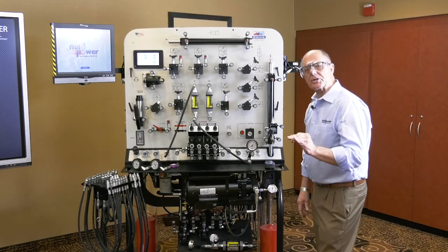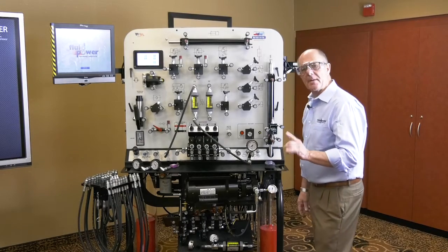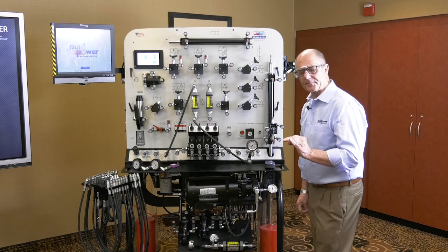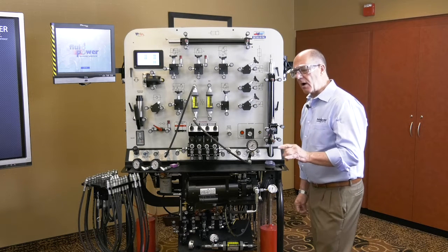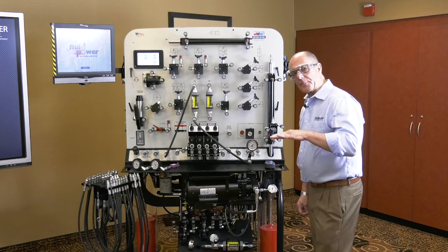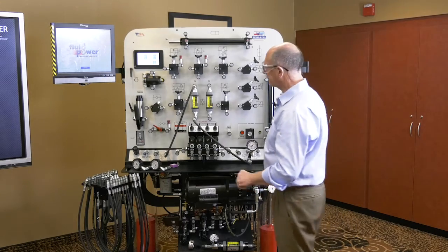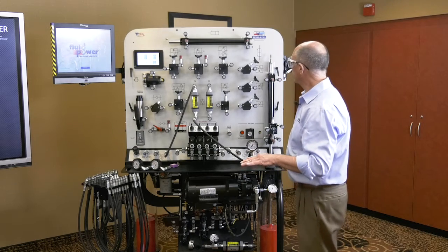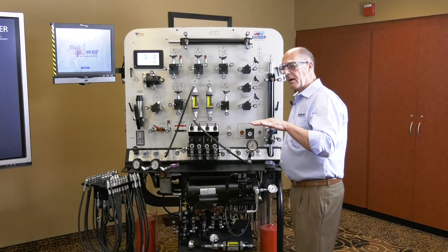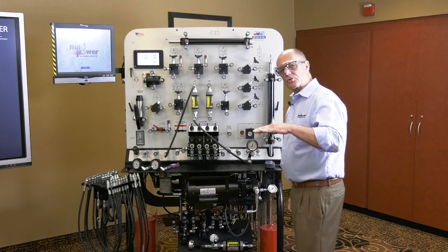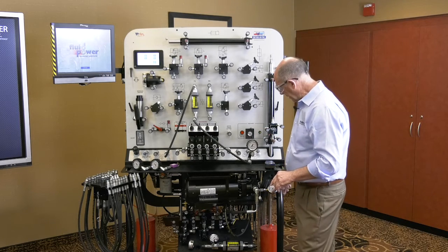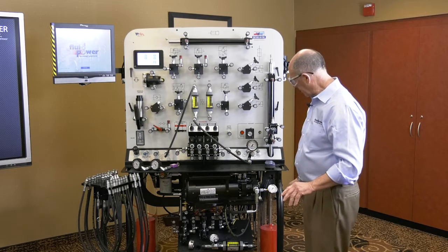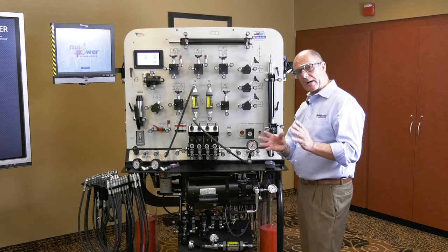The inlet restriction at 1 gallon per minute is 3 inches of mercury. For as long as this pump is operating at this altitude and at this temperature, the inlet restriction that we have just learned here can never change. Never change.